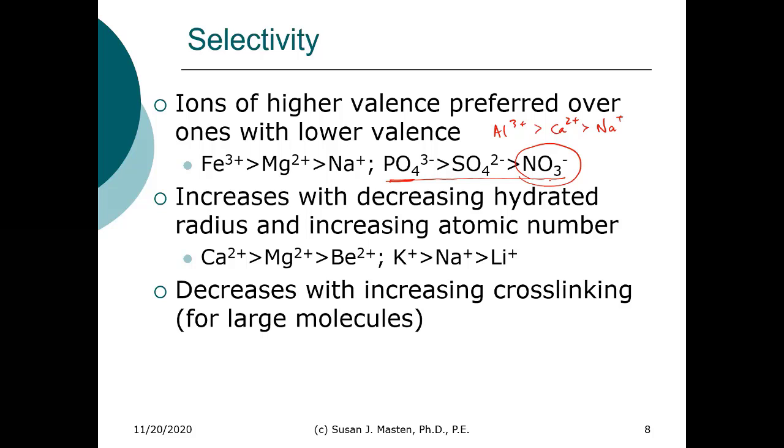So it's shifting the equilibrium from the calcium and magnesium on the resin, releasing the calcium and magnesium into that waste stream and then restoring the resin in the sodium mode so that it can operate effectively again.